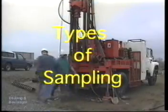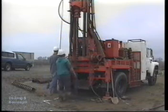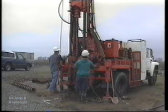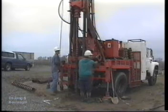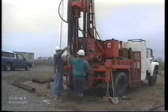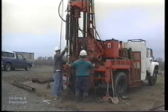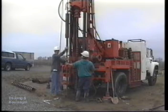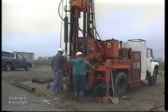We will now discuss methods used to sample soils, thereby allowing the characteristics of soil at discrete points to be evaluated. The choice of sampling method depends on the intended use of the soil samples. Lab measurements of engineering properties such as strength, stiffness, compressibility, or permeability can be strongly affected by sample disturbance. However, time and costs increase rapidly as the degree of sample disturbance is decreased.